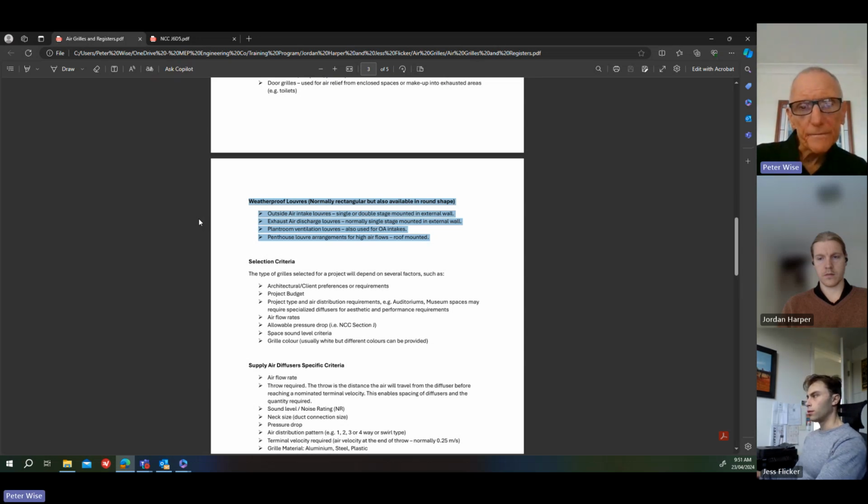It wasn't big enough, and it caused the contractor all sorts of problems because there was pressure drop, there was water being dragged into the building because the velocity was too high. You know, it's quite an important thing to be aware of. So as we go through this session, I'll give you a few tips on how to select them.